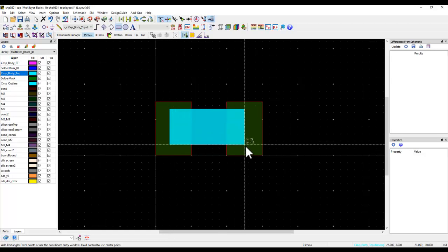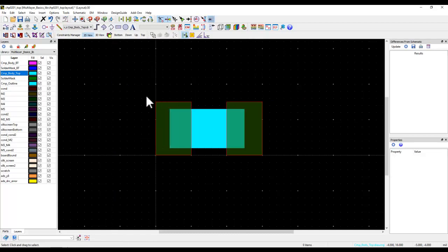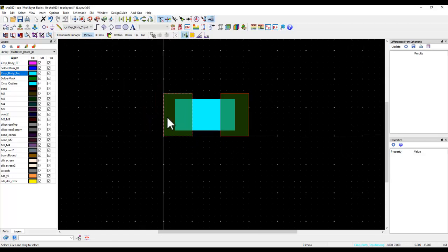Right, so this one is going to represent my component body outline. So I'll go ahead and insert a rectangle there. Now, once I have my footprint basic shape, we need to connect the pins, because ultimately this footprint will be used by a 2-pin component such as inductor, capacitor, and resistor.